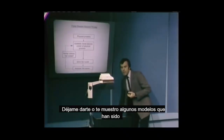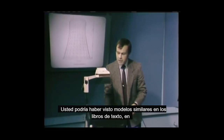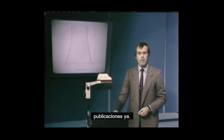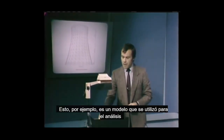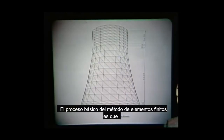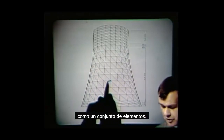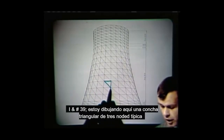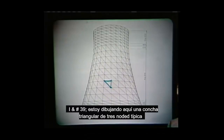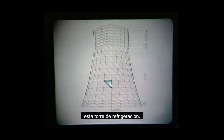Let me show you some models that have been used in actual structural analysis. You might have seen similar models in textbooks, in publications already. This, for example, is a model that was used for the analysis of a cooling tower. The basic process of the finite element method is that we are taking the continuous system and we are idealizing it as an assemblage of elements. I'm drawing here a typical three-noded triangular shell element that was used in the analysis of this cooling tower.